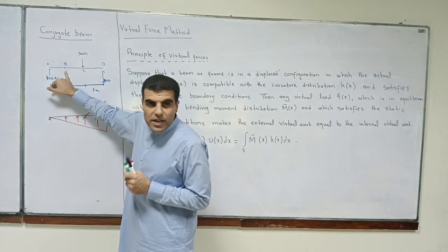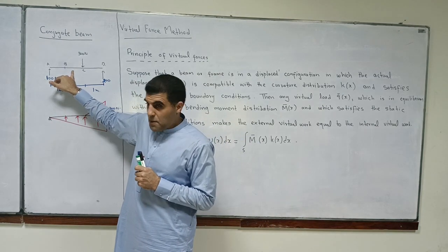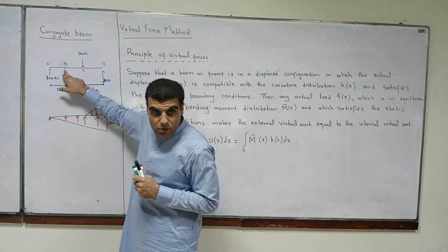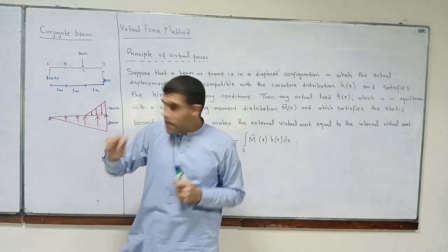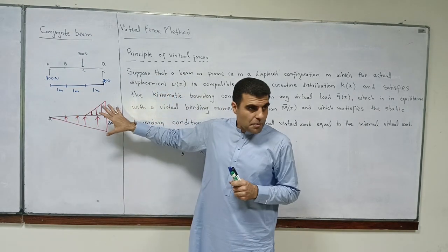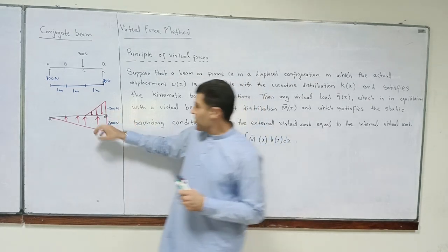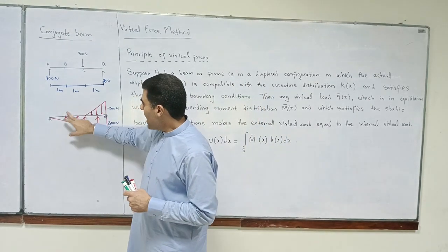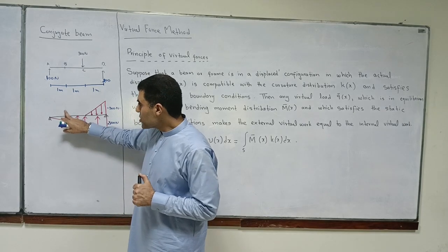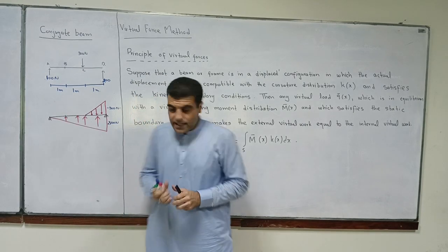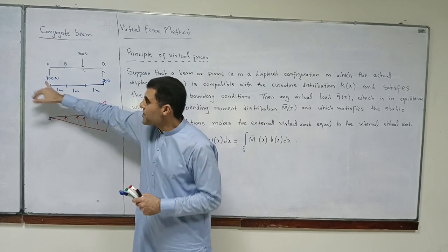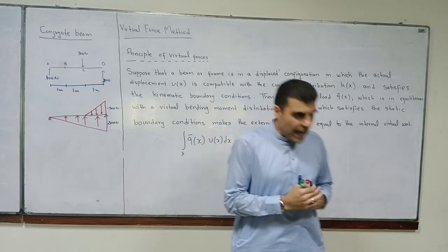For example, in the previous class we were interested in the deflection at point B. We drew the moment diagram by parts, placed it on the beam, and then worked out the shear and moment at point B, which is 1 meter from the support point A.